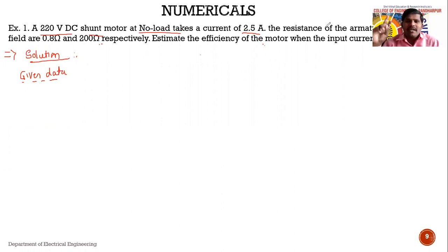After calculation of constant losses we are able to calculate the efficiency of that particular machine at any desired load by the Swinburne test. We are not putting the machine on that much load, we are just assuming that desired load.